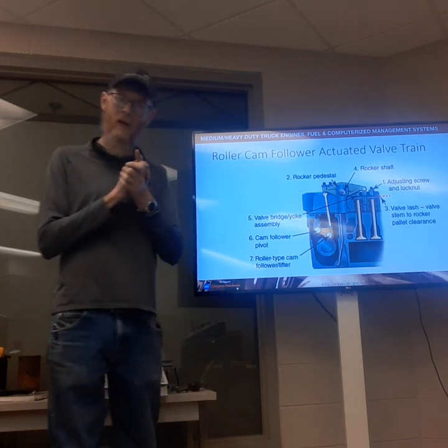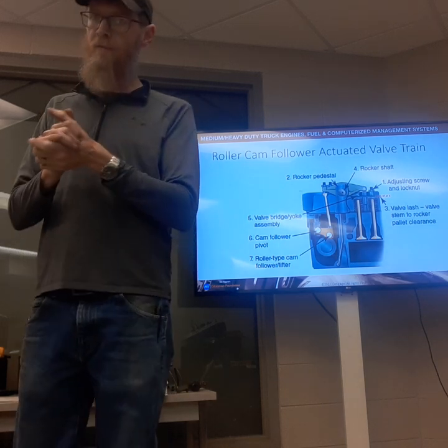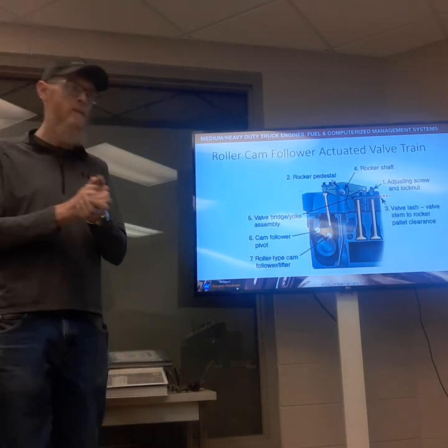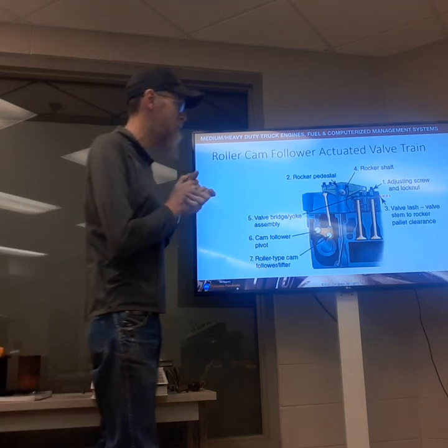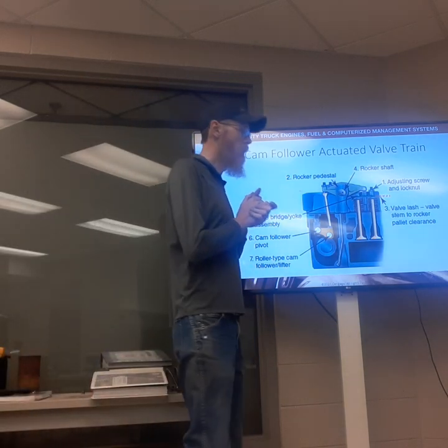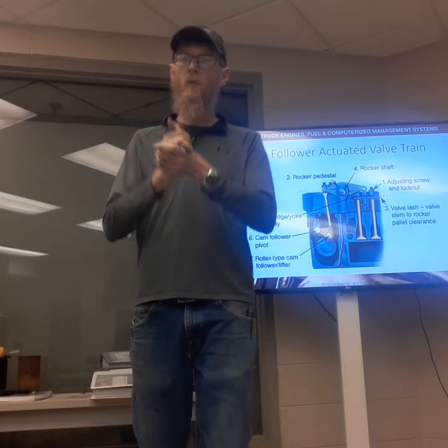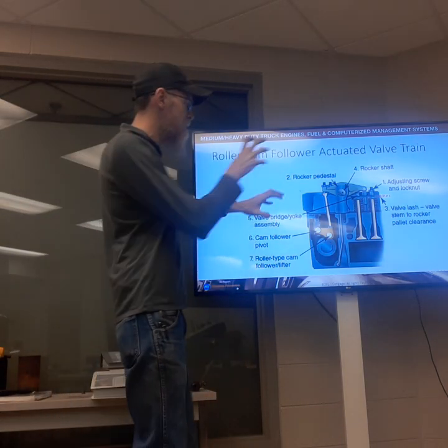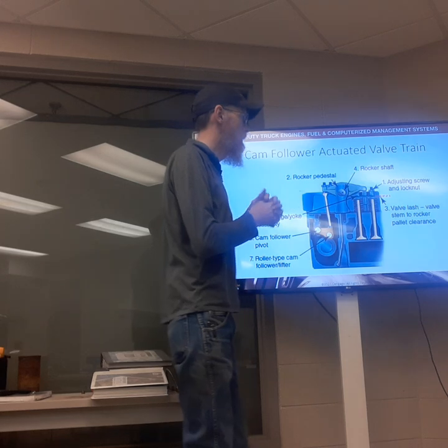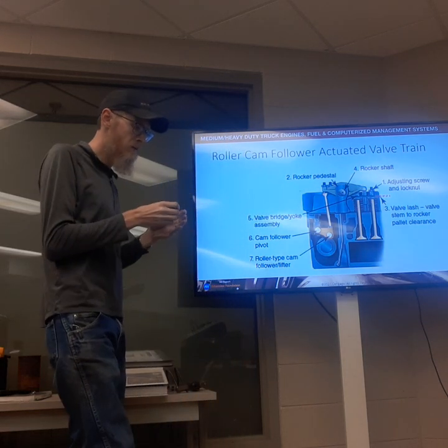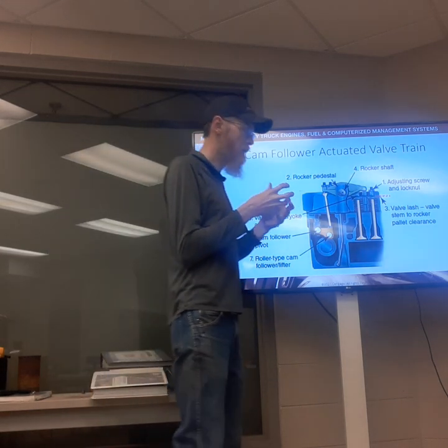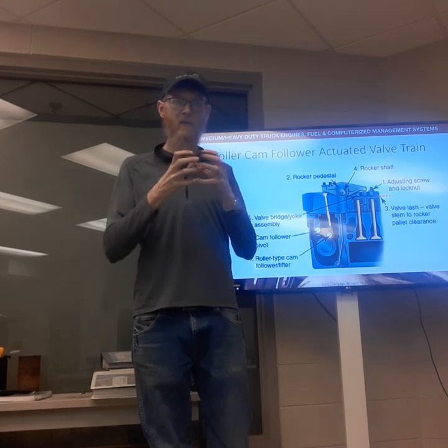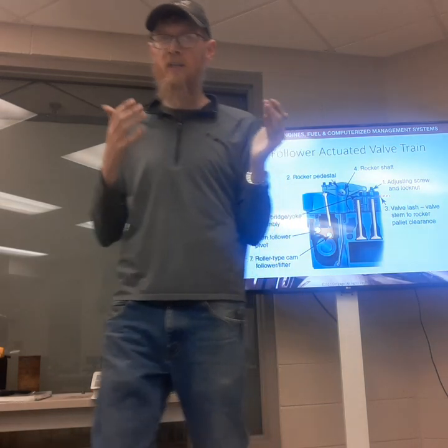I don't know if you got to the point with Joseph, when you were here in the shop, of doing lash adjustments. We talked about that briefly when you were with me, and that is making space between all these parts so that when everything gets hot and all our components expand from that heat, we call that thermal expansion,